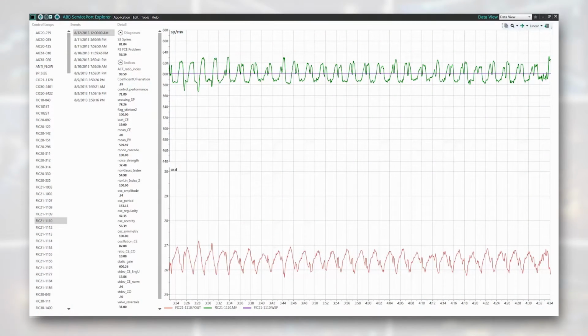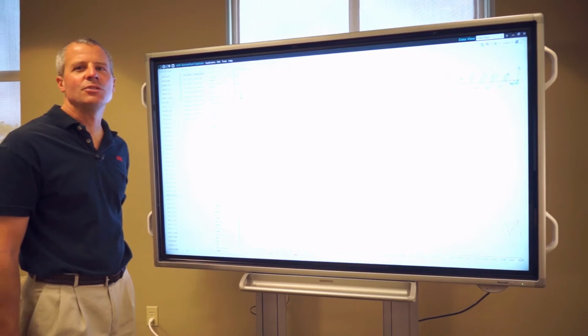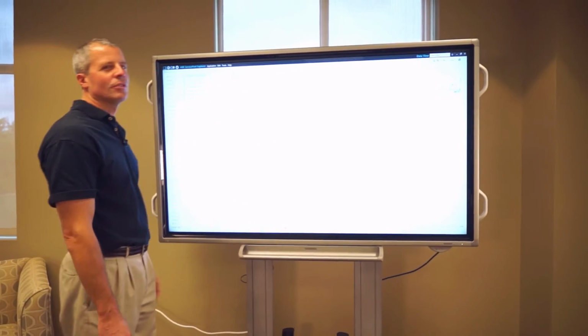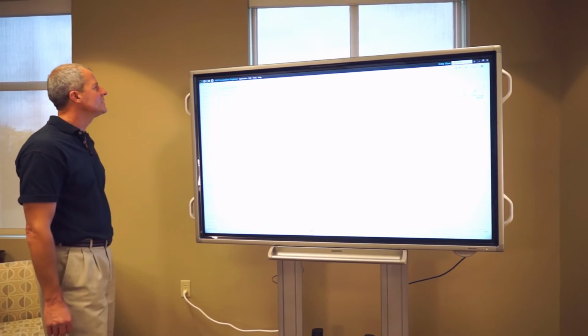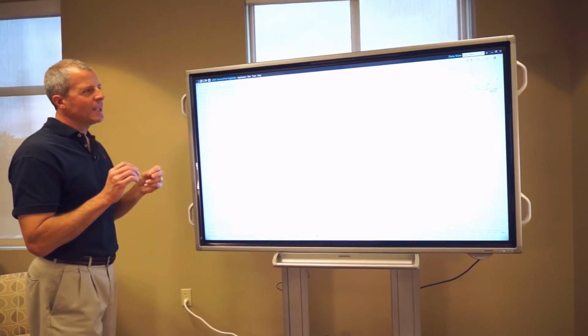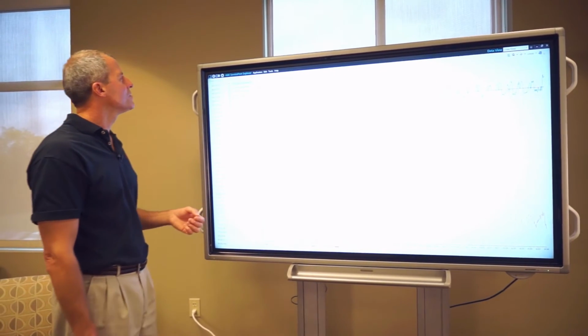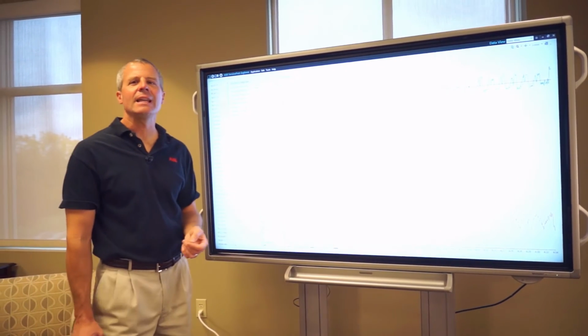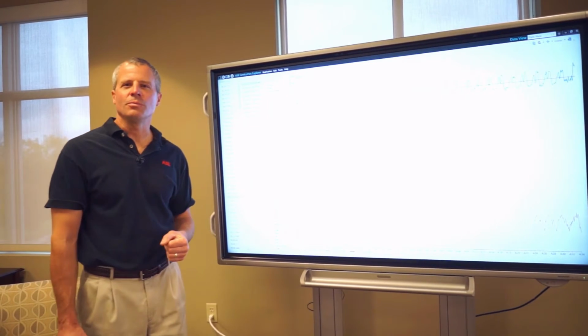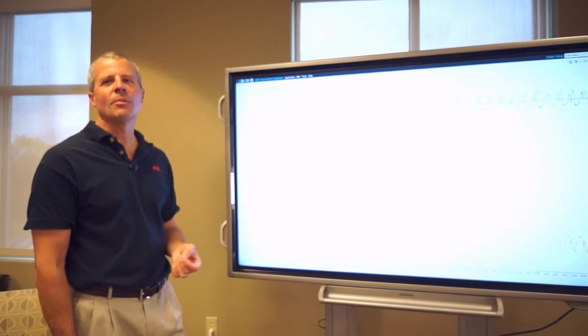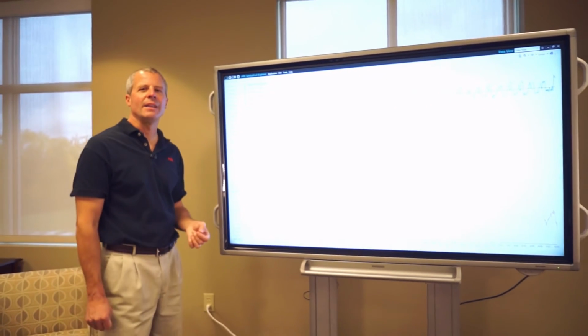The nice thing is the loop channel gives you the scan view to say here are the KPIs you need to investigate, but you can actually get right into the data and look at the data for the particular analysis that you're trying to see. So again, thinking about all the loops that you have to analyze, there's 300 and some loops that you're looking at in this case. We can drill into one loop really fast and identify where the actual issues are and come up with a corrective action plan based on that.